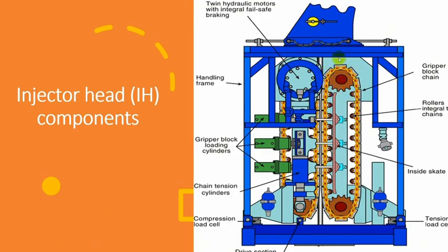in reverse directions. So this sprocket will drive in this direction, clockwise, and this one anti-clockwise. This is in case of running in hole with the coil tube. In blowout of hole, the reverse, this sprocket will rotate anti-clockwise, and this will rotate clockwise. When this rotates, it rotates a chain in yellow color. This chain is connected to this idle sprocket, so it rotates it with its rotation.